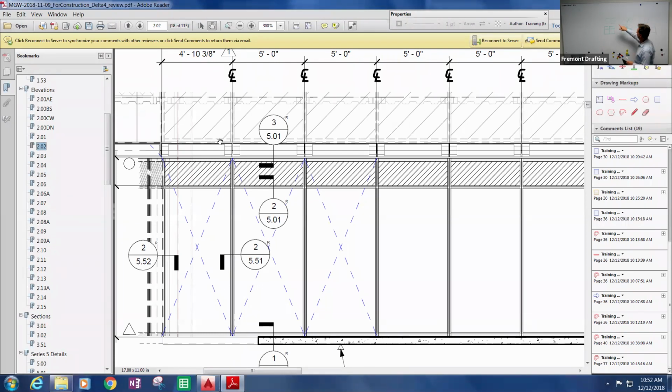And so then this is an issue for us for glass, because the glass stays square. So now I've got rectangular glass and a parallelogram opening. And so in stick walls, there's different engineering we do for the glass, making sure there's clearances and glass isn't going to hit, that we don't necessarily do on unitized. Because on unitized, the opening has stayed the same as the glass, and so there shouldn't be any issues with that on unitized. And yeah, so for us, windows always rack.